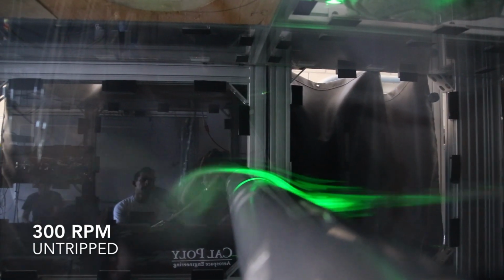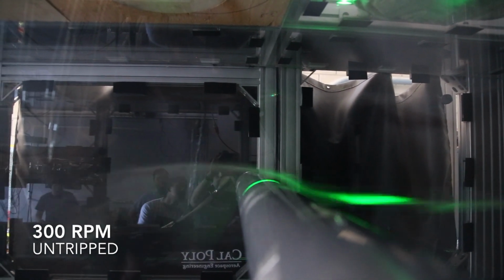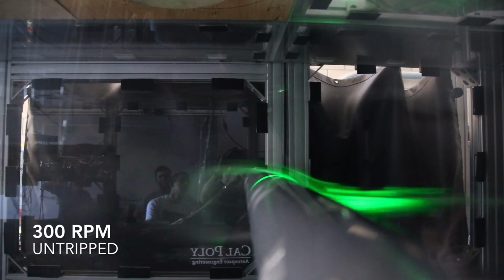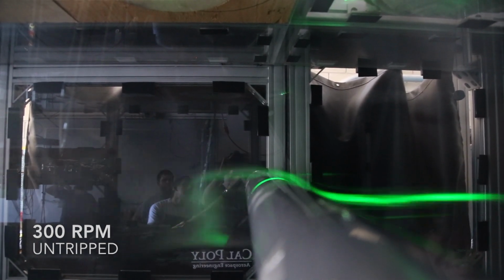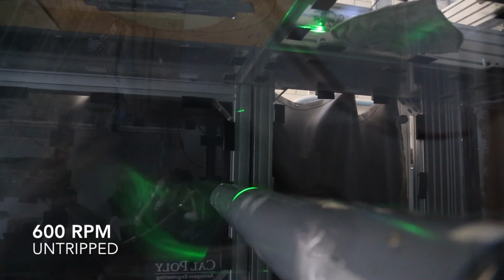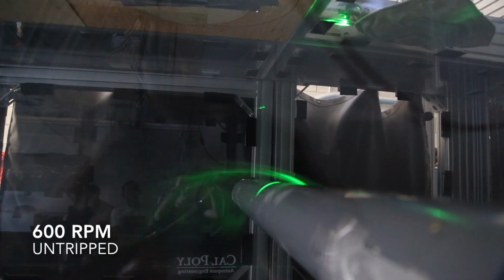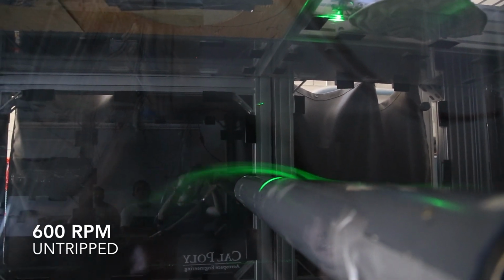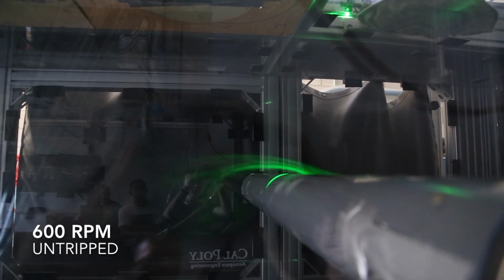The assumption of smooth flow at the trailing edge to meet the Kutta condition is not accurate because of the viscous flow. Unlike the ideal scenario, the viscosity of the flow will result in a thin boundary layer adjacent to the cylinder. The flow separation occurs because the flow in the boundary layer is losing energy due to the viscous friction between the boundary layer of the air and the cylinder's surface. A trailing wake forms on the downstream face of the cylinder.